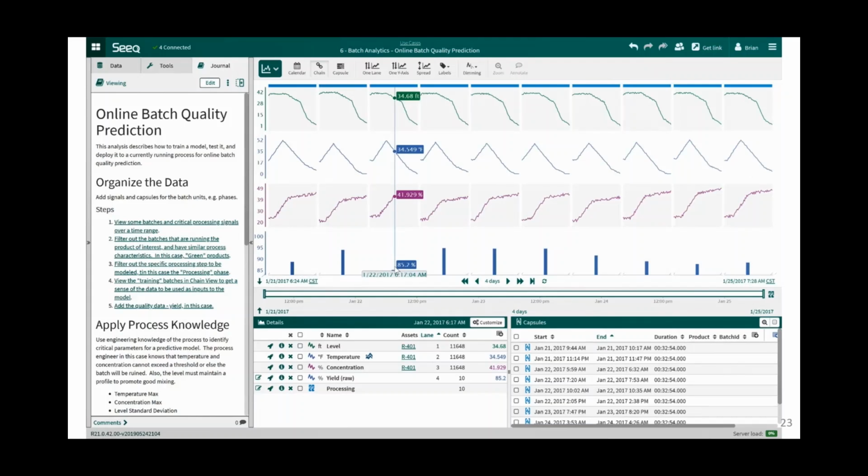We have over 10,000 samples for each process signal and only 10 samples for the yield quality. You can see the counts in the details pane. This equates to approximately 3,000 samples of data to predict one single value per batch. So how do we create a model from this? We can do it. Let's apply our process knowledge to create engineering factors that contribute to the yield and reduce the dimensions of data so that we can model a single point per batch.